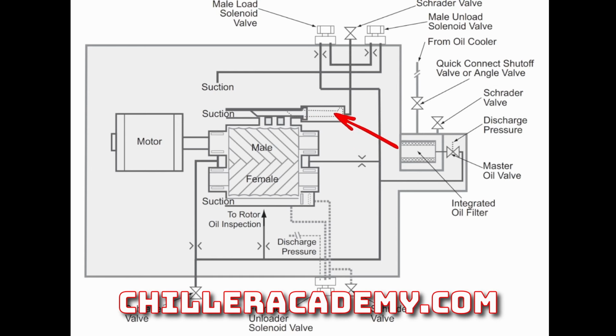This mechanism is going to control how much load gets put on the compressor. So at startup, this slide valve will be in a fully unloaded position, which in this particular case would mean it'd be slid all the way fully forward, where it's got kind of the ghosting here. That would be the fully unloaded, which means that these little bypass ports are allowed to bypass around the rotors, and this back piece is not able to make compression. We're only allowing compression on part of the rotor assembly.